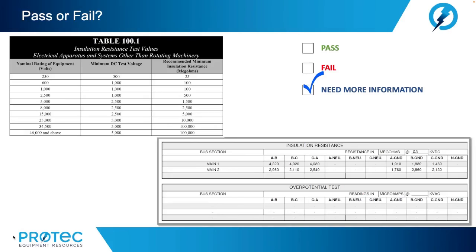So this raises a question. Was the switchgear isolated from the incoming and outgoing bus? And are we dealing with just these very short sections inside the gear? Or was the incoming and outgoing connected to the remaining bus systems, in which case we might be talking significantly longer busway systems? As we learned, we need to know the length in order to get a good comparison to the reference tables. So, again, length is going to matter in our overall measurement, and we're going to need to be able to correct accordingly to get an accurate comparison to the reference tables.